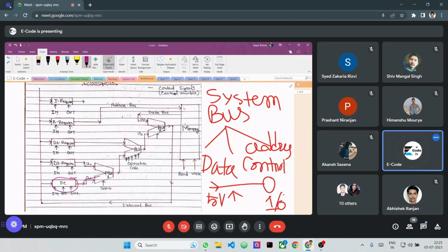If I want to send this value, we have to send 1, then it will pass the value of PC. Then we have to do nothing here. We just tell it to take this input and pass it through. This will directly do nothing, no computation, no calculation, and pass the value through it. This multiplexer will also send 1, so send the value.